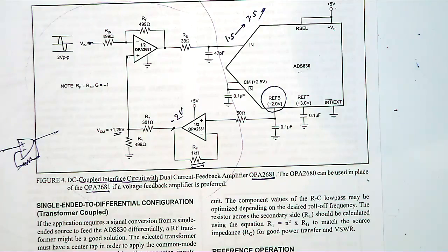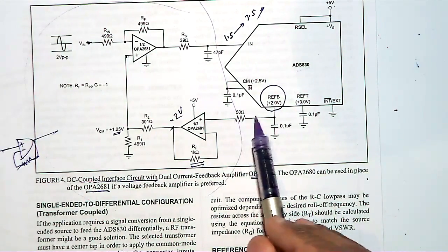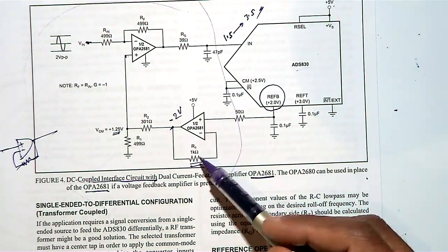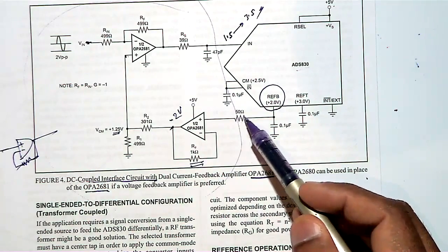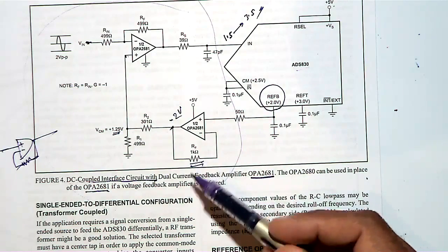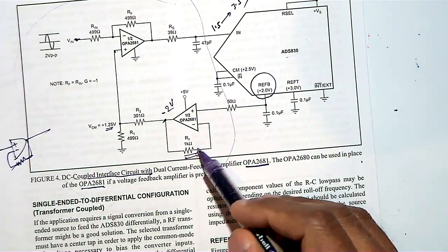That is for the impedance compensation. If you have some impedance issue, people will connect this buffer to make sure that it is matching with this impedance. That is the reason they connect some resistance here, for impedance matching, because here you are connecting an impedance and then you have to match it. Sometimes when people build it practically, some issue will be there, then they will recommend for this particular op amp you connect this one, otherwise there will be an impedance matching issue. That is the reason in the buffer they recommended connecting a resistor here.